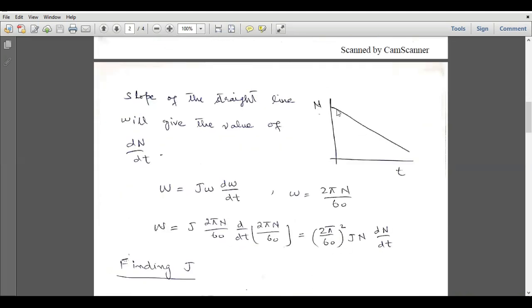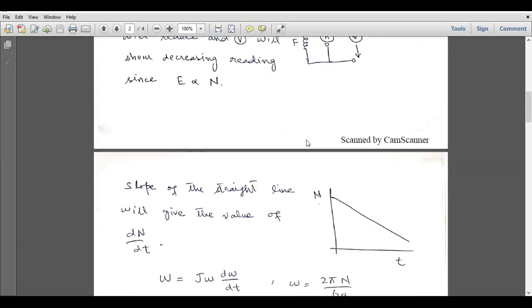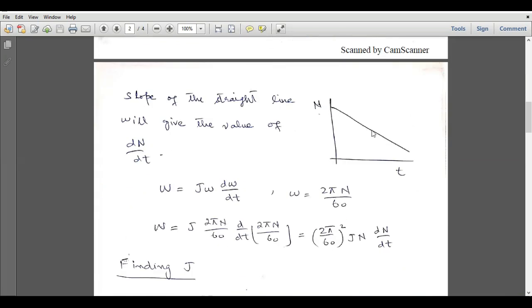So we can get such a decreasing curve for the induced EMF or voltage, and since this voltage is proportional to the speed, we can find the constant of proportionality, and then we can easily get the same curve of speed by only having this voltmeter. So after having this running down curve of the speed, we can calculate its derivative, and then we can calculate these stray losses at any speed of the motor, right?